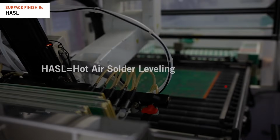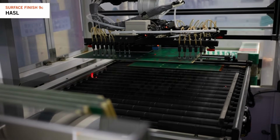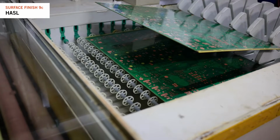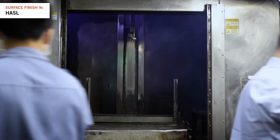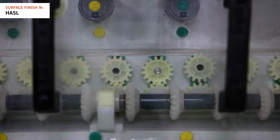Hot air solder levelling, or HASL, for both leaded and lead-free processes is a common PCB surface finish that provides a surface finish which is similar to the solder used to solder the components. It's important to note that the surface is not as flat as ENIG or immersion tin, making it unsuitable for fine-pitch SMD components. First, we clean the PCB to make sure that the copper is ready for solder.